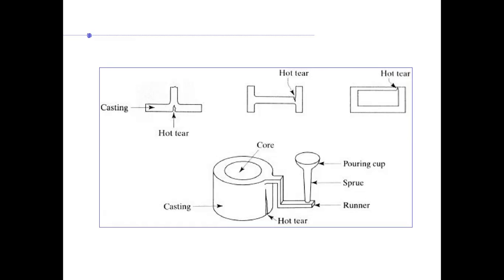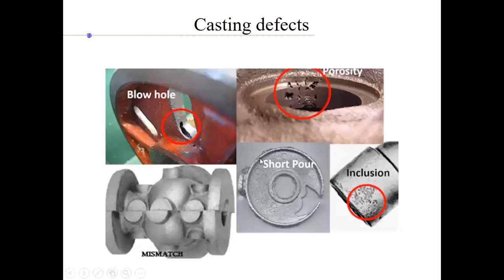We have not covered chills, right? We'll see that; it is there to achieve directional solidification. I had mentioned briefly, if you remember, that it is there to give directional solidification, right? I've included this slide just so you can understand better. You see porosity. You see that it is unable to completely fill, and you have those holes because of the escape of gases, and that was not completely filled. It should have been filled by the riser. It's not filled. No holes, right?